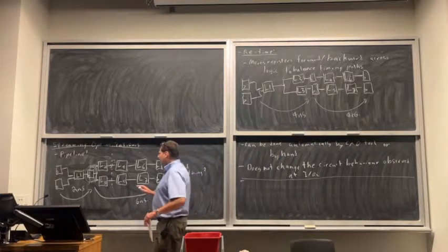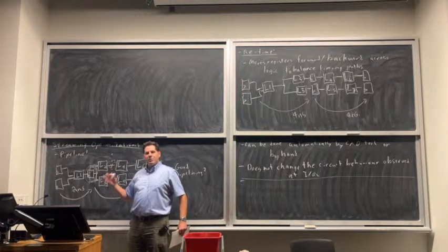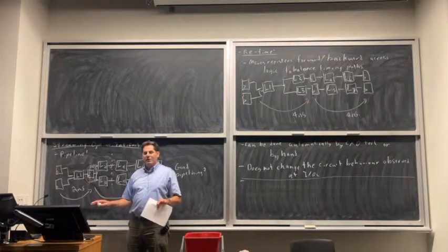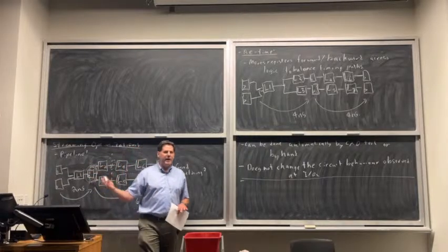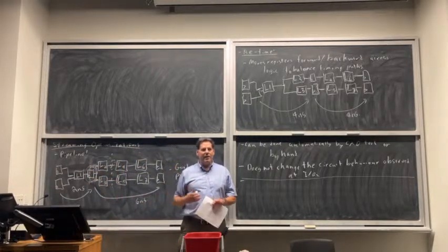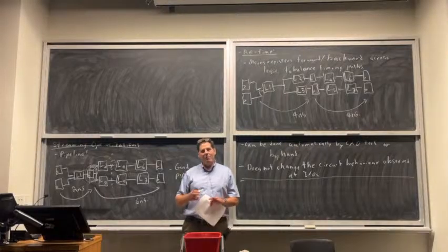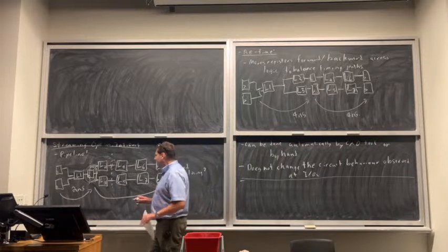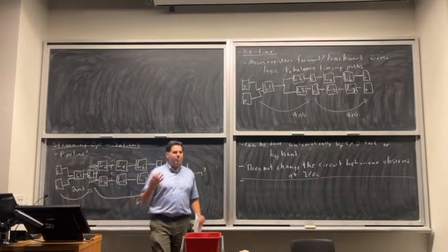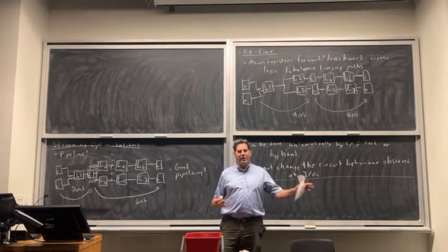Later on, when they get near the end of placement and routing, they know the delays pretty well at this point, but it's harder to actually move registers around because you might be duplicating them and you have to reinsert that into the placement, which is basically done. So you have more information about what to do, but it's harder to reinsert. That means the CAD tools are not perfect at this at all. Early on they're guessing.